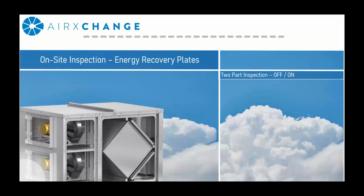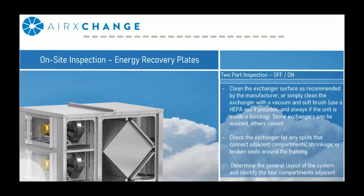Okay, so moving over to devices that use static plates. Once again, this is going to be a two-part process. So with the system off, you're going to want to start by cleaning the heat exchanger, using the manufacturer recommended process. The most common ways, once again, are either vacuuming or potentially washing. Air exchange plates require vacuuming, and I'll go over that in a few slides.